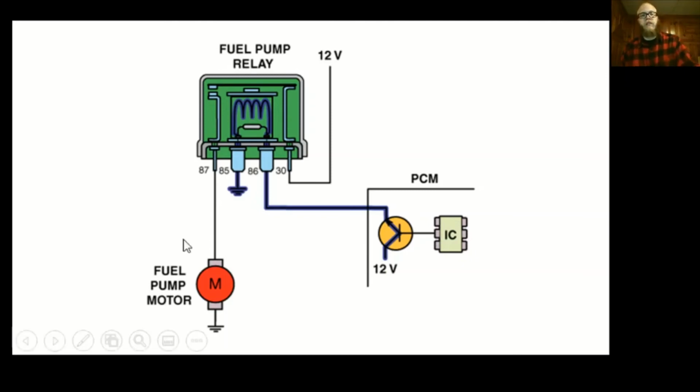And it also makes it so that we can very quickly control this relay to be on or off and allow for a returnless fuel system. So we can very quickly turn that on and off. We have a computer making some nice decisions about what the fuel pressure should be, and we don't even need a fuel pressure sensor to be able to figure that out.